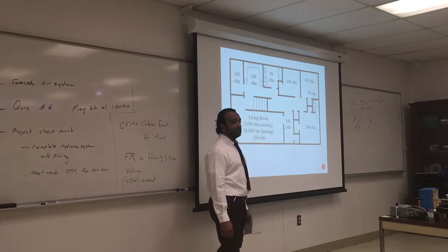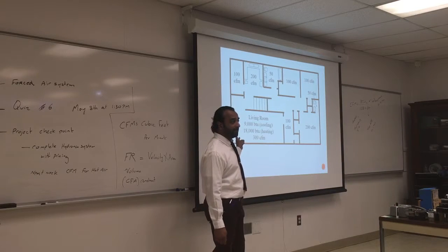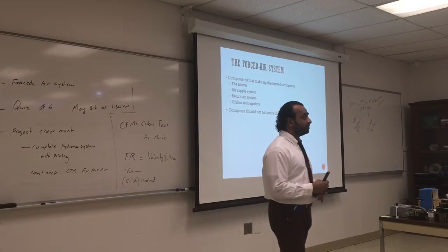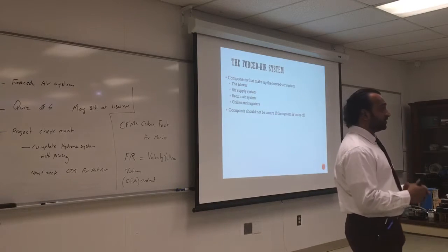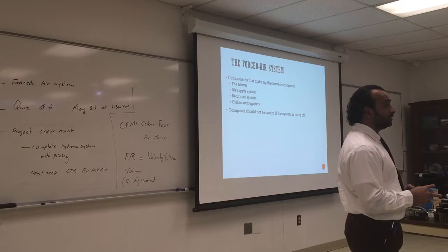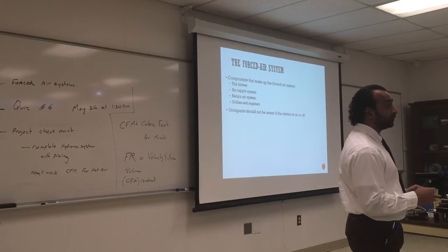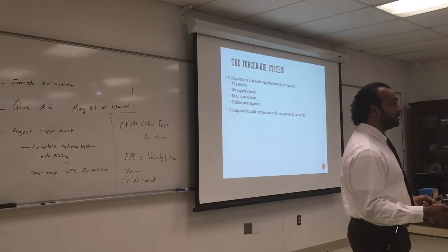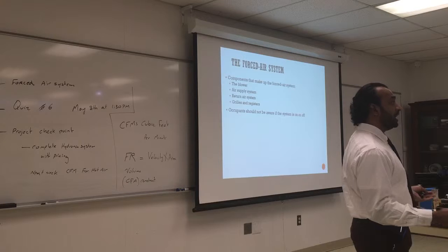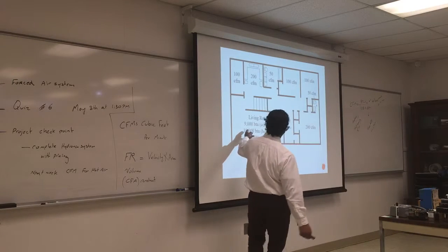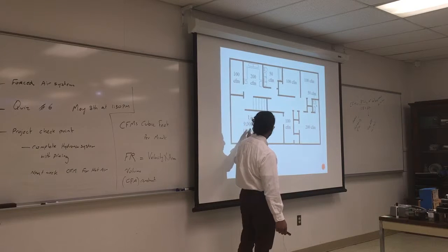And why is that? That depends a lot on the location. And if you did the project, the cooling load, probably you have noticed that the cooling load is very low compared to the heating load if your house is in the northeast. Because in the summertime, it doesn't get that hot for that long. Meanwhile, we turn on the heater in December all the way to June. And it gets really cold. That's why the heating load is much higher than the cooling load.